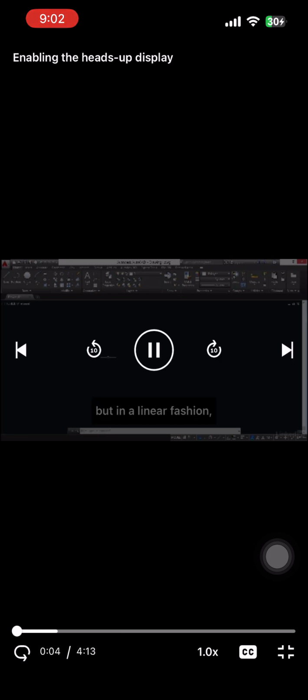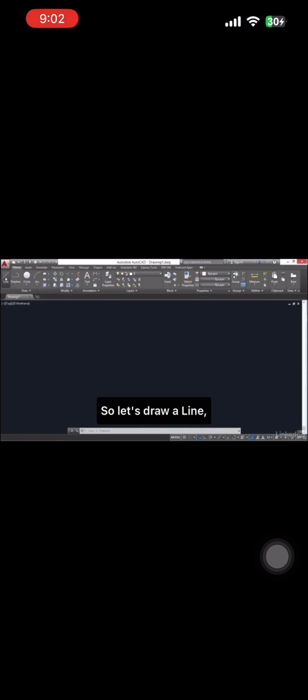If you've been watching the videos in this course in a linear fashion, you've seen me use dynamic input many times. But if you're jumping in here, I'll show you how to use this system, and I'll give you even more detail about how it works. So let's draw a line. And right now, I'm seeing the dynamic input. That's controlled here with this status bar toggle. When that's off, I don't see that information next to the cursor.